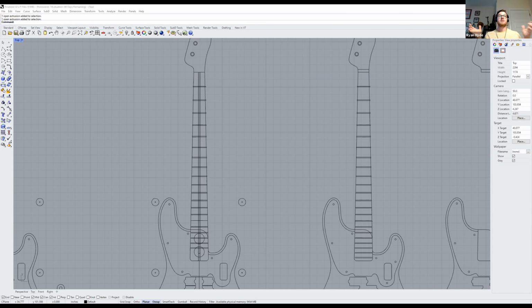You want your material to be as flat as possible on both sides, and you want to make sure it's not twisted. You want it to be extremely rectangular. You want to match the perfection that this sort of program needs, because the program works in very exact dimensions. This is going to be exactly 5 inches. So if your stuff is off, that could mean your registration in the machine is off, right?